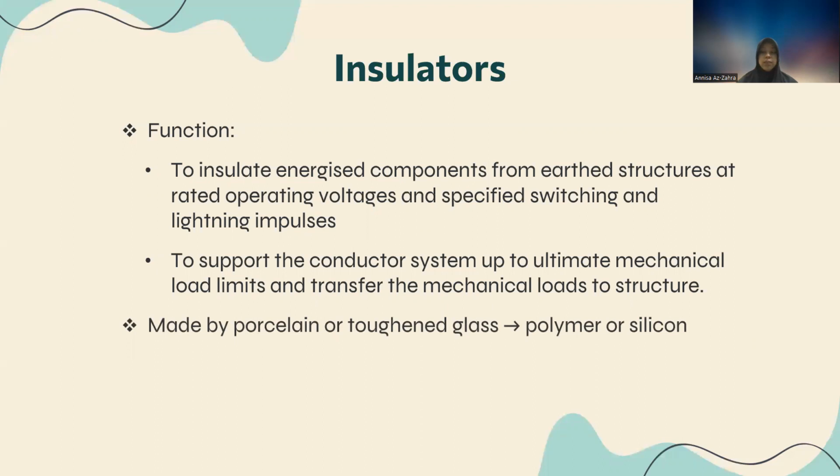Insulators have commonly been comprised of porcelain or toughened glass, which need routine cleaning to eliminate dust build-up that can lead to insulator flashover and noise. And newer insulators are composed of polymer or silicone, which are lightweight and shatter-resistant.